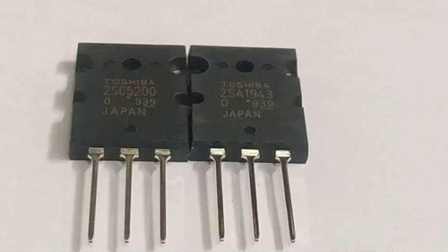Filtering: the output voltage is filtered using an inductor and a capacitor to smooth the switching waveform and provide a stable DC output voltage. Efficiency: switching regulators are more energy efficient than linear regulators because they waste less energy as heat. They are commonly used in applications where power efficiency is crucial, such as in laptops, smartphones, and power adapters.